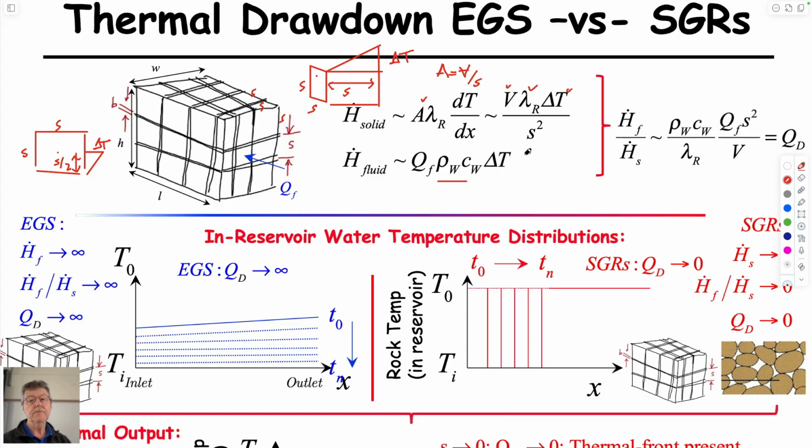So you get a very convenient non-dimensional number. So these are dimensional, I guess. They're not non-dimensional. But you could look at the ratio of those. So if you look at the ratio of how much heat is carried by the fluid and how much heat is carried by conduction. If the heat carried by conduction is very small, then it's not a very efficient heat exchanger in getting heat from the solid into the liquid. And so you can just take these two expressions, divide one by the other.